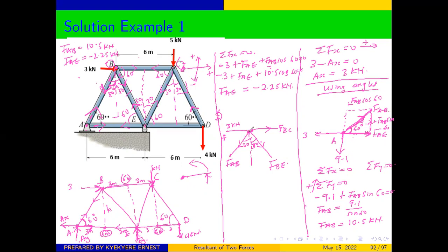You can see that we'll be moving down on Y. Therefore, our Y component is going to be negative, and from there, we're moving this direction on the X also. Therefore, that component will also be negative. Our X component for FAB will be negative. The angle is 30, and you can see that the 30 is facing our X component. Therefore, our X component for FAB will be equal to negative FAB sine 30.